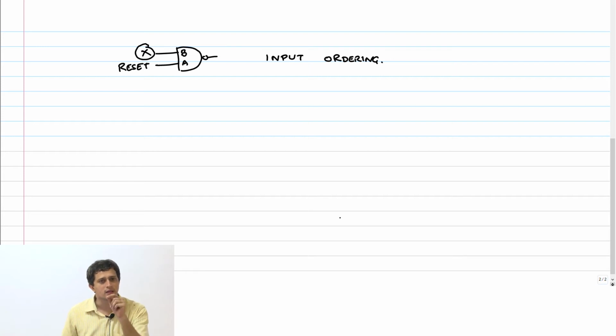Now I can take this one step further. Input A is very critical. Reset is not a critical signal. It's going to happen very few times. Okay. So now let me see how I can improve the logical effort of this input X. Right? The question I'm going to ask is, should this NAND gate have a sizing of 2222, or can it have something else where I can help the signal X to switch faster? Okay, so let's look at that case now.